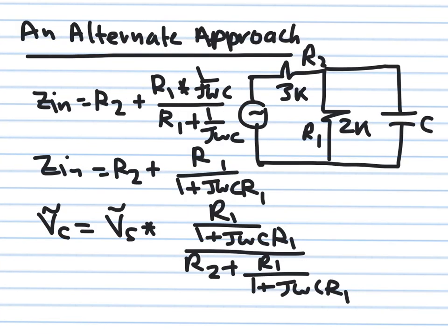Now we spent some good time on this example. We wrote the differential equation, we used the complex response functions, we eliminated the e to the j omega t, we wrote the phasor, we got its modulus, we got its angle, and so on. We could have done the same without having to go through the differential equation at all. So how do we do it? You consider this one as an impedance, and then you have two impedances in parallel. We treat them as two resistances in parallel, and I will show you why this is the case later. I'm just jumping ahead a little bit to show you that we can get the same answer in an easier approach.